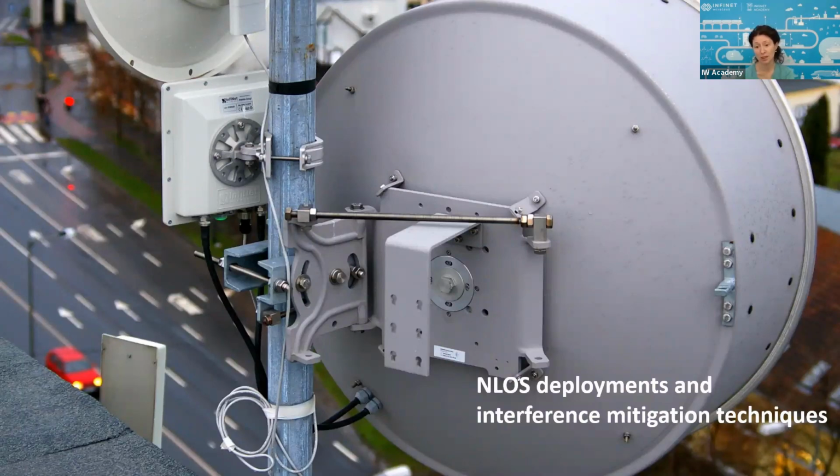For scattering, do we need to use maximum power if you have the link across a pine wood? You should use maximum power only if you have problems currently on the link, not by default. So it's not a default recommendation because the link can work fine with less power, and less power means less interference, and you extend the lifetime of the device. Okay, so use maximum power only if you have problems on the link using a lower power, not by default. If you install a link over a pine wood, you should set maximum power. This is not a statement.